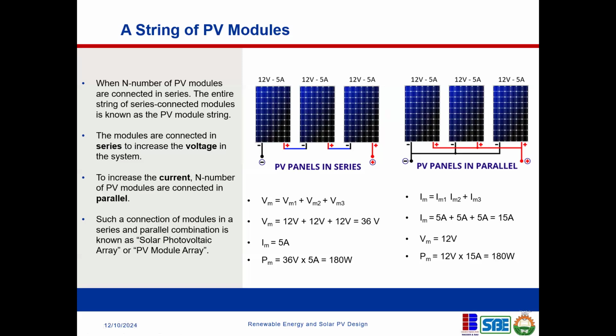Okay, so I just need to re-emphasize this shading effect on solar panels so that when you're designing, please pay attention to shading, because it creates a lot of problems in the design of systems. When you do your solar installations and some part of the panels are being covered by shading, maybe by nearby buildings or whatever it is, and you don't take that into consideration, it can greatly affect the entire output of your solar panel.